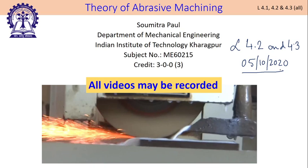So, what we are going to learn today is about HM. HM is maximum uncut chip thickness, or it is the maximum grit depth of cut. By whichever name you call it, you can use it. Maximum grit depth of cut is kind of a legacy name, whereas maximum uncut chip thickness is a name which can be used across grinding, machining and everything.